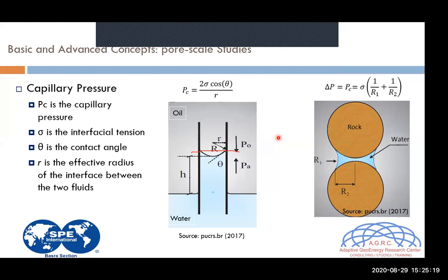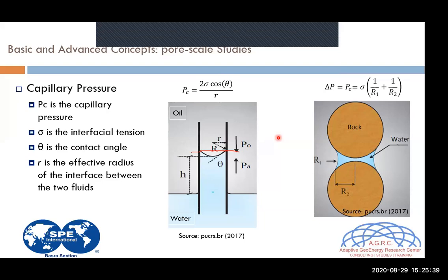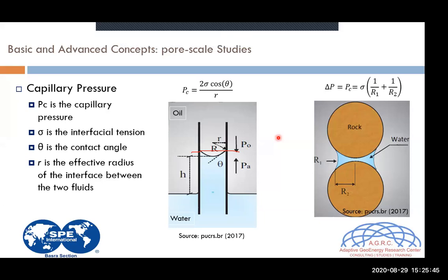But yes. Of course, when we are dealing with this kind of simulation, you have to be aware about the density, viscosity, contact angle, a lot of different information. I mean, during the lab calculation and measure, they also take in their consideration the reservoir fluid itself, like the oil inside the reservoir, the water salinity, for example.